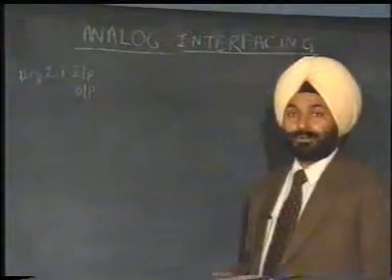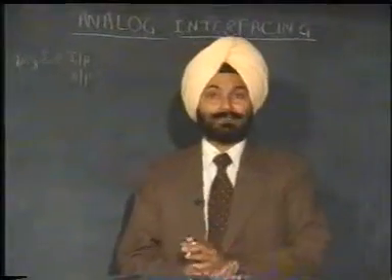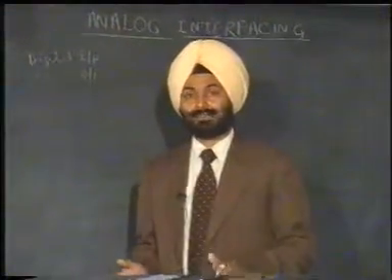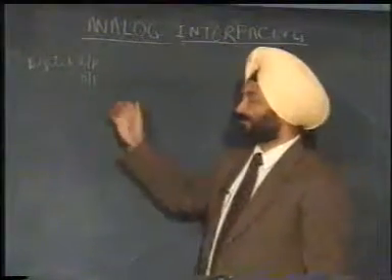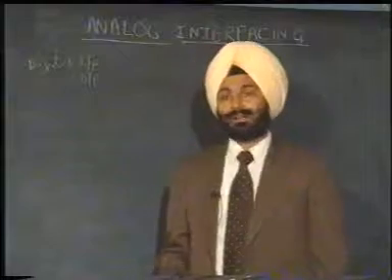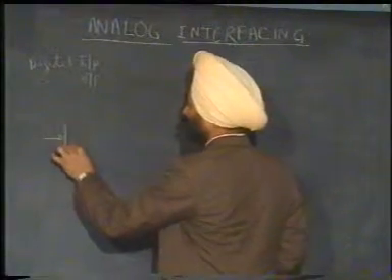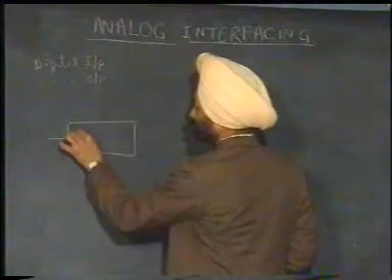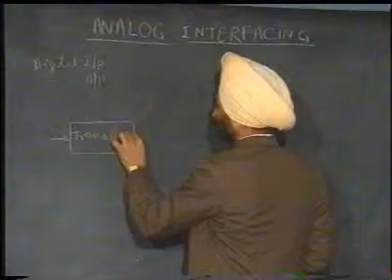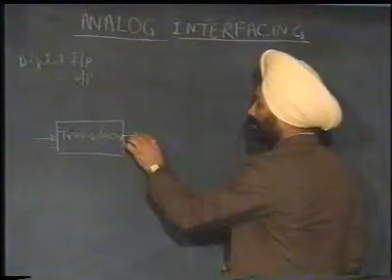So if we have to process the signals through the digital system like the one based on microprocessor, we have to present the signals accordingly and accept the signals in this form. The signals in natural form are normally continuous, and by the use of a transducer, they can be converted into an electrical signal.